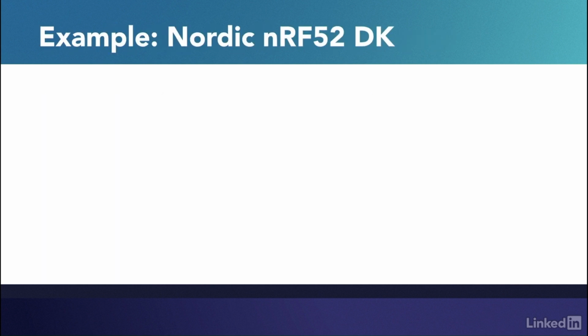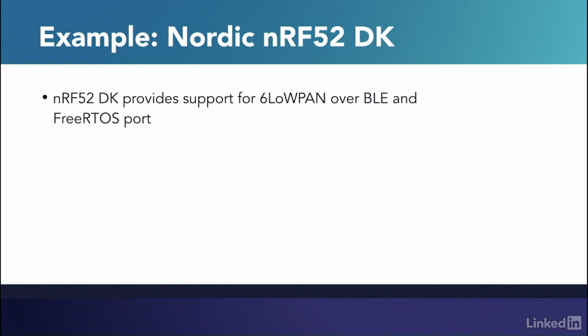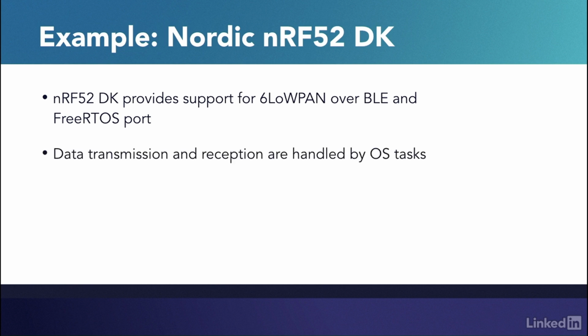A recommended way of using Bluetooth, including BLE, is using the SDK provided by the vendor of the Bluetooth chipset. Taking the nRF52 development kit from Nordic Semiconductor as an example, the support for 6LoWPAN over BLE is contained in the SDK package for that kit, where it supports some nRF development boards out of the box. On the other hand, how to manage the data sending and receiving tasks is handled by an OS. For example, if we use FreeRTOS, we can define different tasks and assign